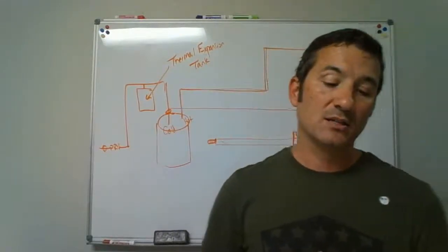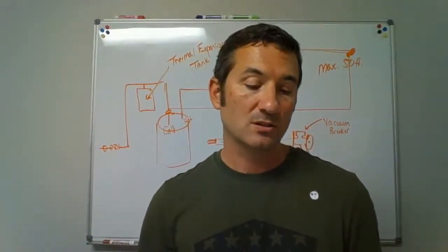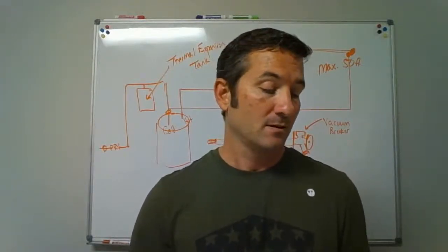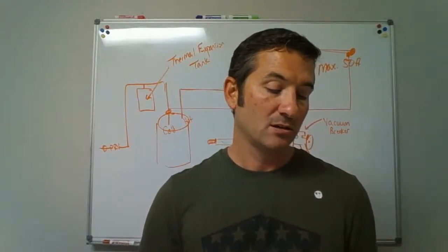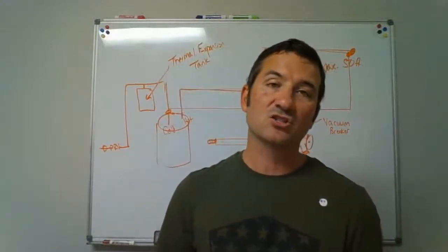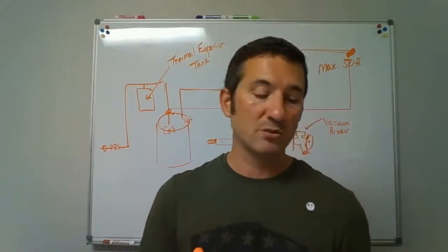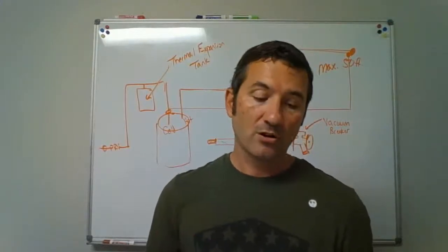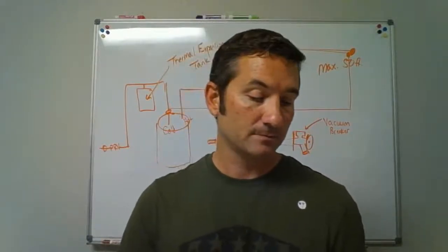Just as a note, here's some places you can look: 608.13.6 or 608.15.4. Okay. Use those. Question 13. A vacuum breaker is not allowed to be installed under an exhaust hood. Is that true or false? True or false? Once again, look at 608.15.4 to find that answer.